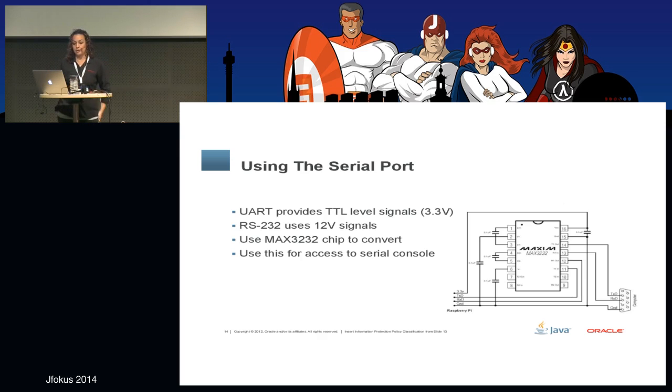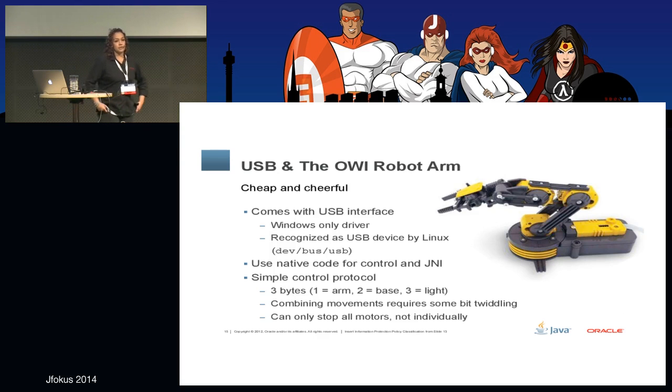So a very straightforward project. We also tested the USB interface. With the USB, we tried this little robot. And the idea with USB is that most of the drivers come for Windows, but if you connect a device and you can actually see it, you should be able to talk to it. You end up normally doing native code and then a JNI wrapper around it, and then finally you can actually use Java to connect to it. So again, if you recognize the device, check under dev bus USB to see if you see it, and then you should be able to go into some native code and JNI and finally Java.